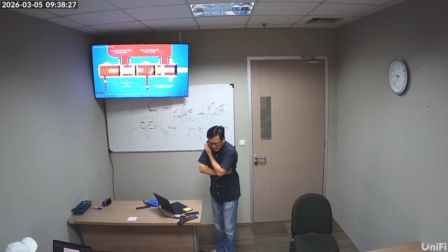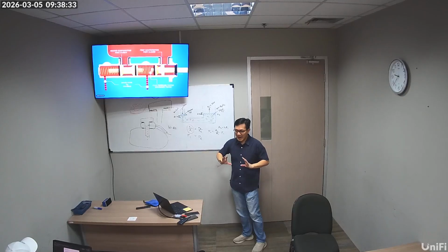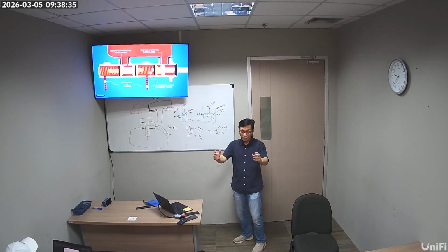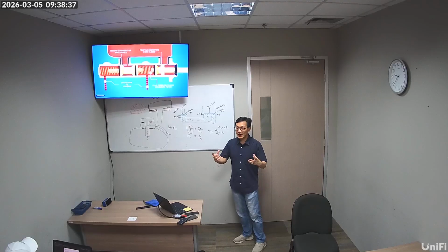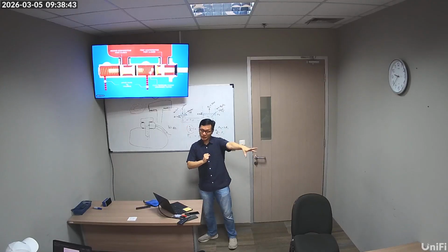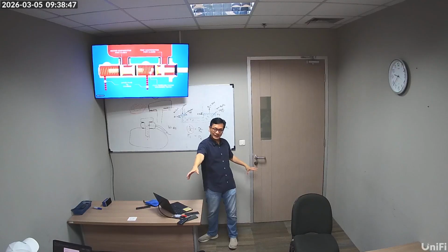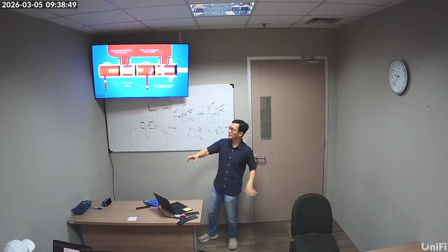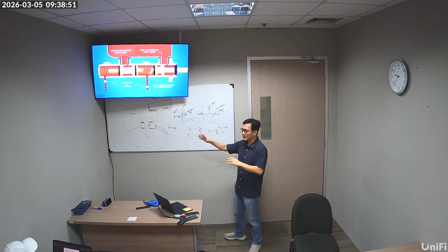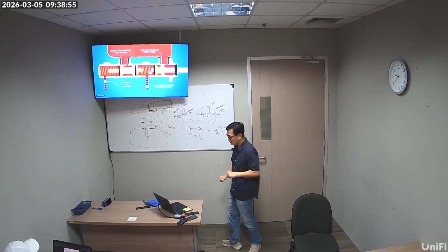Okay, now these two ports are connected sometimes to the front and back. So one goes to the front, one goes to the back. Oftentimes they are actually in a diagonal arrangement. So one port goes to the left front and right rear. The other port goes to the right front and left rear. So if one fails, you get more symmetric braking.